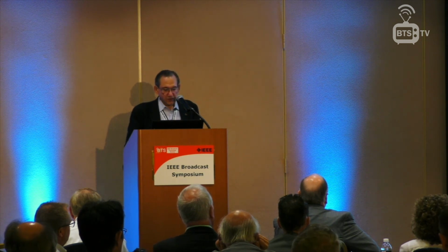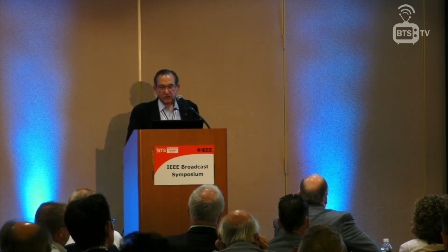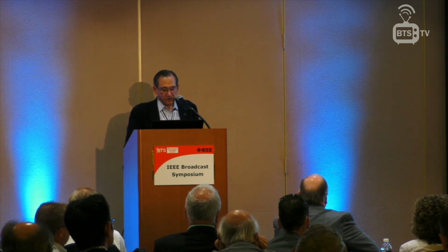For channel 14, the issue is to protect land mobile. There are three sources of the interference: the transmitters, PIM in the environment, and receivers. Transmitters and receivers can be treated with filters, but PIM means cleaning up the environment. And interactions with the land mobile operators will be part of the process. And that's it. Thank you.